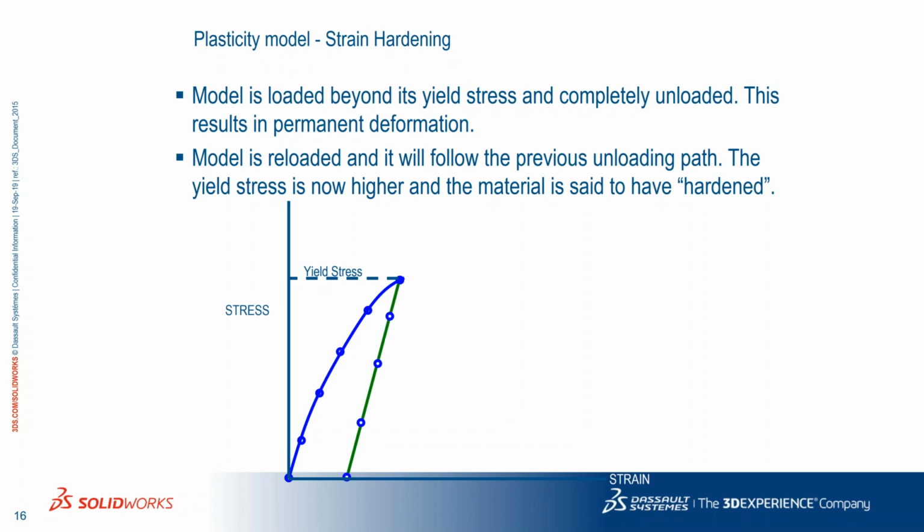So you will get a permanent deformation. Here you can see it on the strain. So this is plasticity. This is an effect that you want to understand. How to do that? Basically, you need, in this case, more points above the yield stress in the plastic zone.